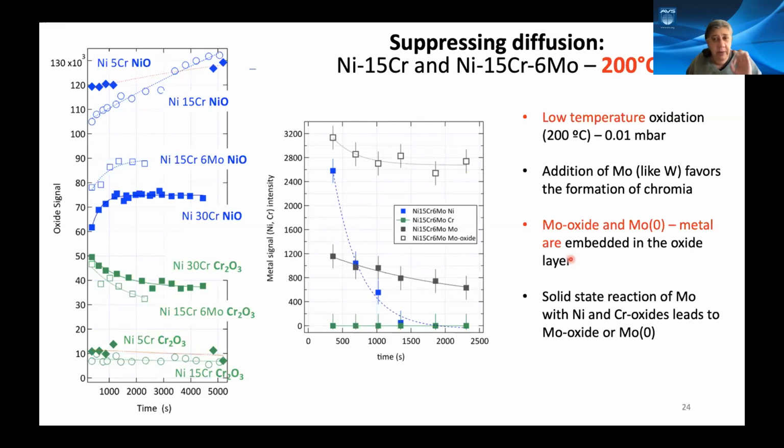We have found in the literature no indication that you will have massively faster diffusion if you have a ternary. It can be that it's just grain boundary diffusion, and we need to compare that to single crystal materials, how that plays out. However, at 200 Celsius, nothing moves here anymore. I mean, that is really a very, very sluggish motion within the bulk.